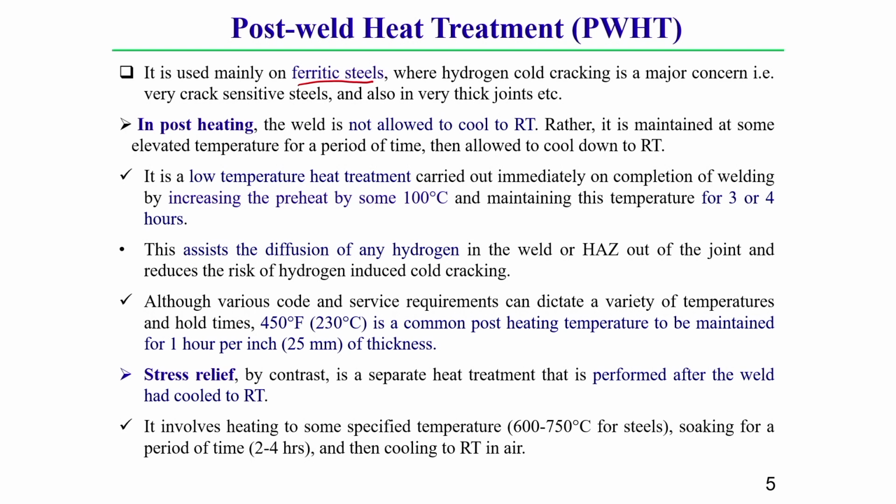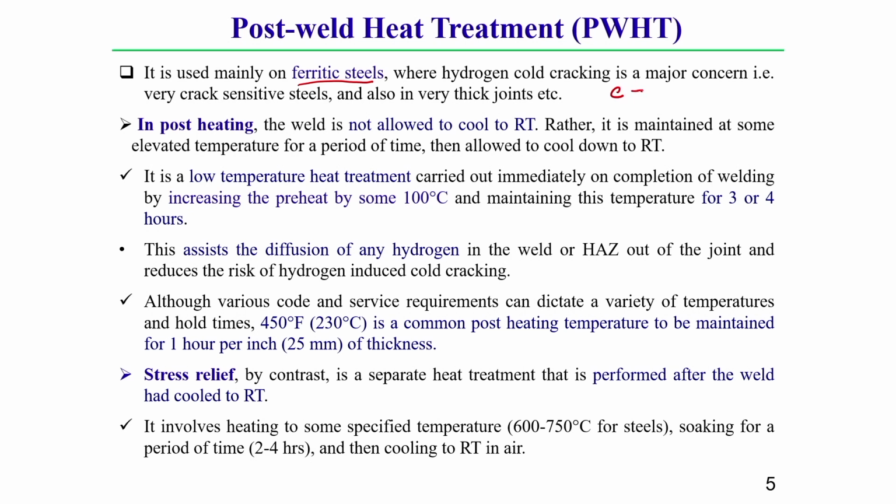I am explaining it a little. In ferritic steel, the carbon percentage varies from 0.08 to 0.2%. Silicon is around 1%, manganese is around 1 to 1.5%, and for stainless steel, the chromium percentage is 11 to 27%. Here I am just discussing its properties.